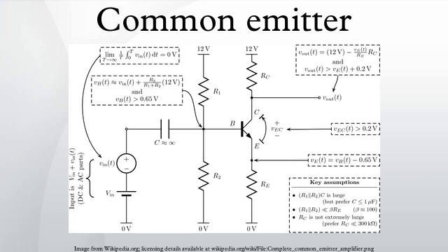amplifier. Emitter degeneration. Common emitter amplifiers give the amplifier an inverted output and can have a very high gain that may vary widely from one transistor to the next. The gain is a strong function of both temperature and bias current, and so the actual gain is somewhat unpredictable. Stability is another problem associated with such high-gain circuits due to any unintentional positive feedback that may be present. Other problems associated with the circuit are the low input dynamic range imposed by the small signal limit. There is high distortion if this limit is exceeded and the transistor ceases to behave like its small signal model.